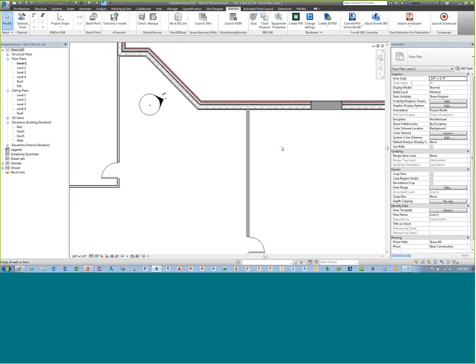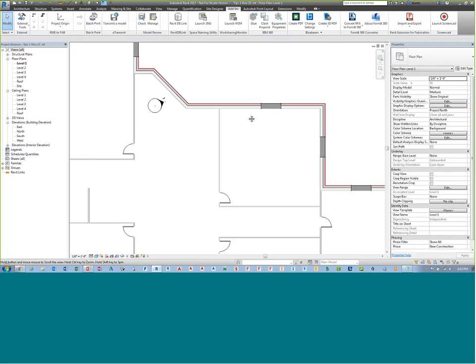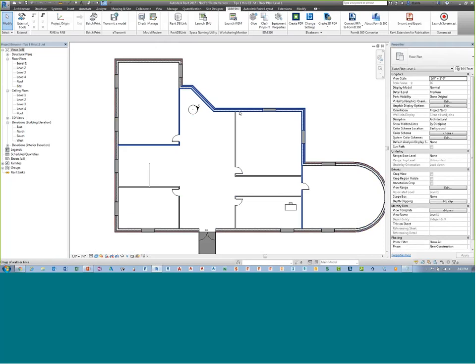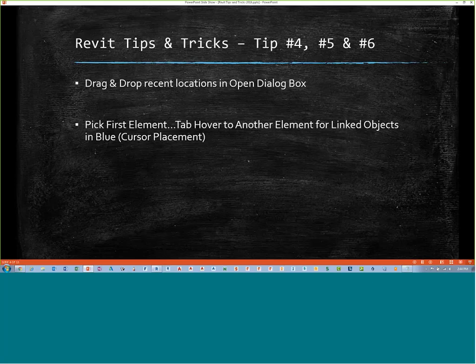If I zoom in here, and I put my cursor on the inside wall, or the outside wall, and I tab, it should jump in sequence between showing the connection between that wall, for example, this grouping here, or this outside grouping there. And if I move my mouse from the lower bottom south end of the wall, you'll see certain walls are highlighted, versus if my cursor is on the outer north portion of the wall, it's highlighting a different set of walls. So just be cognizant of the tabbing and where your cursor sits.